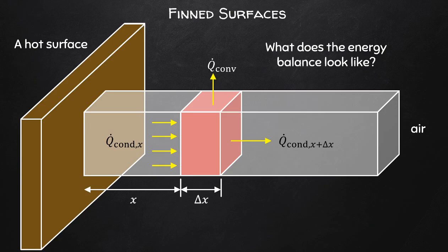Think about fins as an increase in surface area through which heat can be conducted or convected away. So it's conducted through the fin and then convected over the fin surface into the fluid in question. So the more surface area that I provide, the more energy can be dissipated. Alright, so the source of the heat is the hot surface, and this provides like a sink, and then the heat travels through the fin and gets convected away.